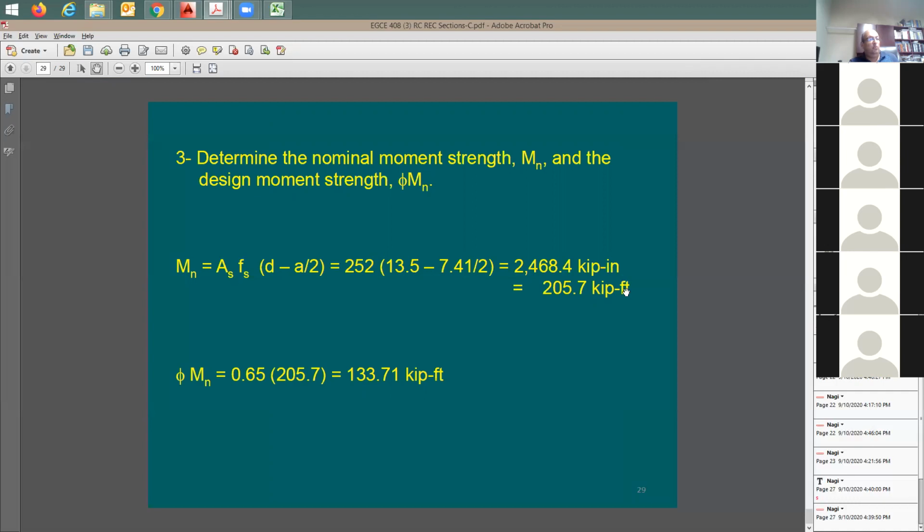Because what do you need this rebar for? I'm going to be asking you this question. What's the importance of having this rebar? How do you assume the rebars first? Do you start by putting the rebars in the beam, or do you start by having the loads, figure out the moment demand, M sub U, and then say, let me solve and find out A sub S? Which way do you think you would start in an actual practice?